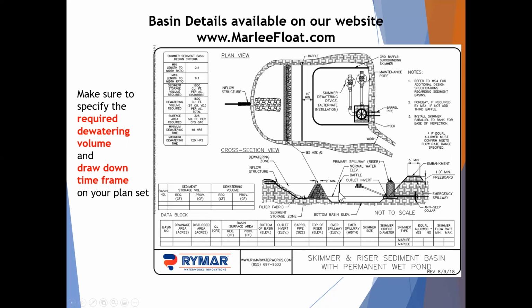So in ours, we provide an orifice plate, and I'll show you this in a little bit, that has specific sizes already established, and we've tested each one of those. The Faircloth and maybe the Ocean Supply, I'm not sure how it does it, has a little plug that the contractor is supposed to cut to a required opening.